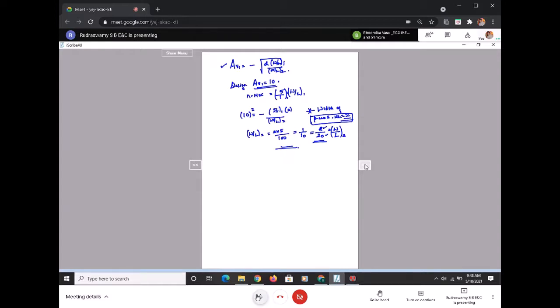Come on, see. Which is the active device that we are using as a transistor? NMOS. Is the PMOS acting as a transistor here, or is it a load kind of thing? Load. Yeah, that's why we are not worried about the PMOS characteristics with respect to width and length here. Is that clear now?